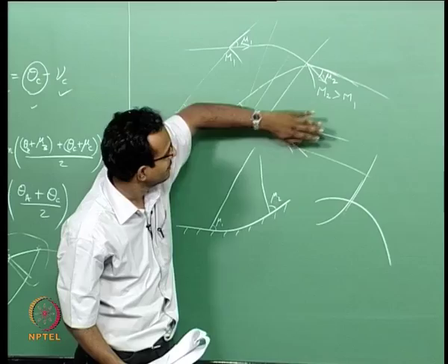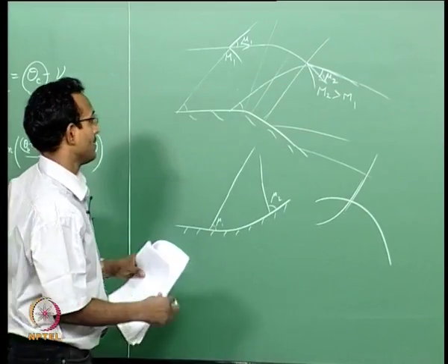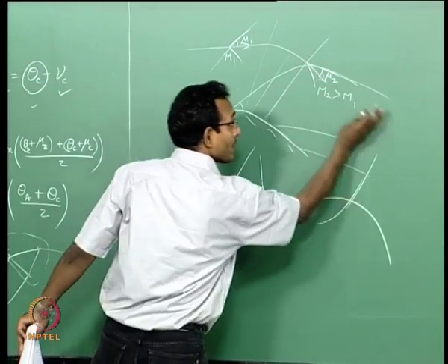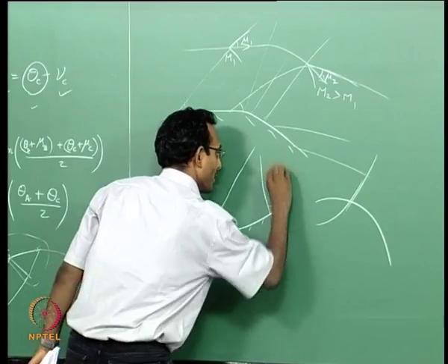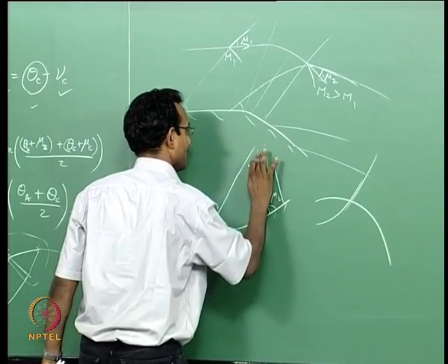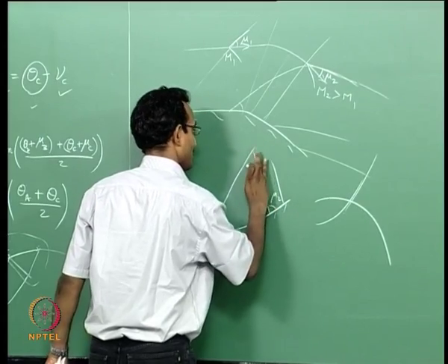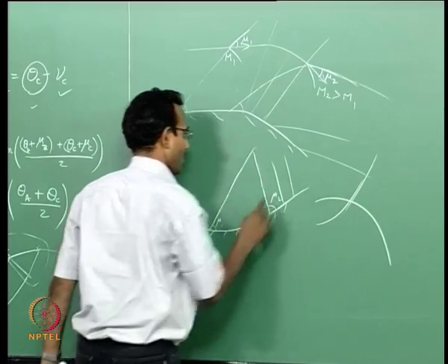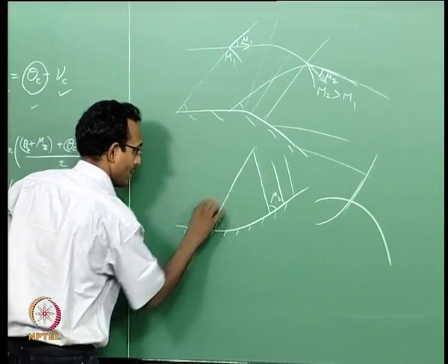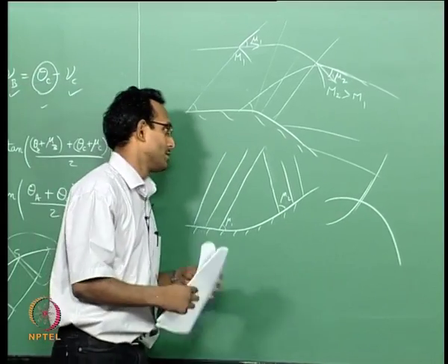With respect to the flow streamline, they are all left running waves. So I am seeing that these will become parallel eventually to that also, okay, which means there is no more change in Mach number in this region. Same thing will happen here. If I draw one more characteristic here, this will be parallel to this characteristic. I am not drawing it exactly parallel, it should be something like this, and they will all be parallel after this point. And what about before this compression? They will also be parallel to the previous value. This is what will happen.